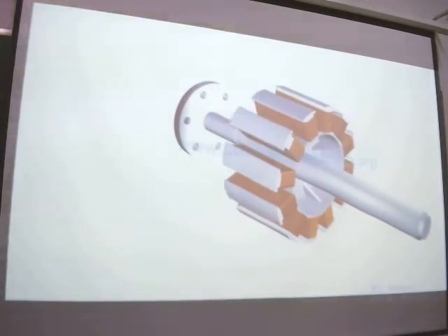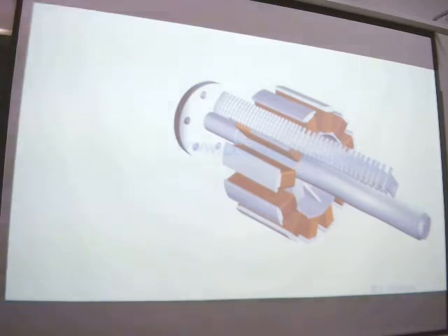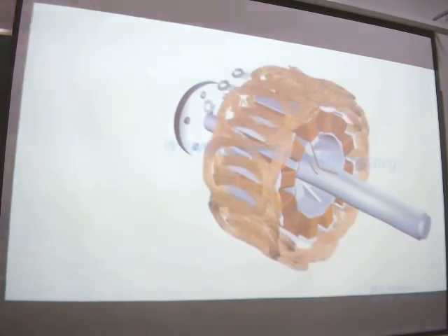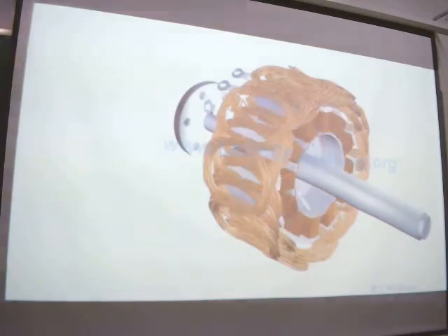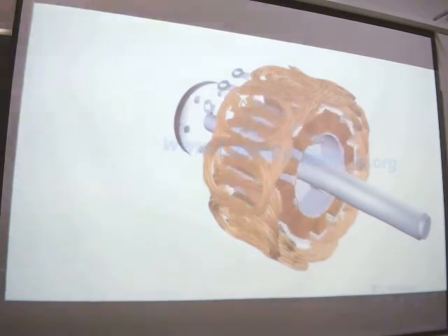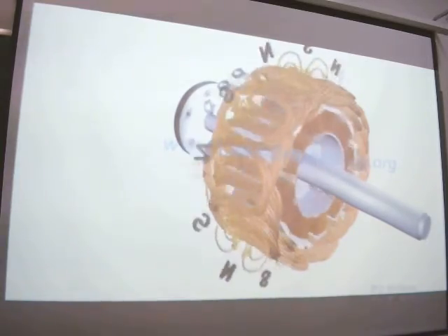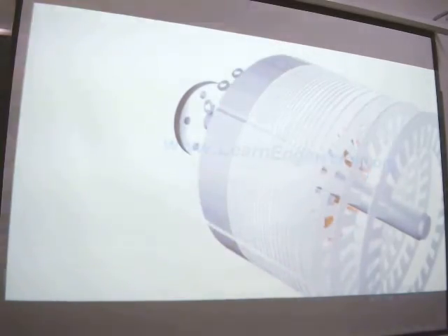Pole core is used to effectively transfer magnetic flux, and they are made with fairly thick steel lamina. Such insulated lamina reduces energy loss due to eddy current formation. Armature winding of a three-phase 12-pole system is shown here. A stator core is used to enhance magnetic flux transfer.